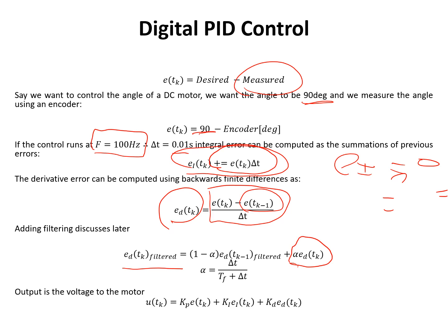And this alpha value is basically the amount of filtering to apply. So for instance, if alpha is effectively 1, then this term will fall down to 0, and our filter output will be the same as the input in essence, so there's no filtering performed.